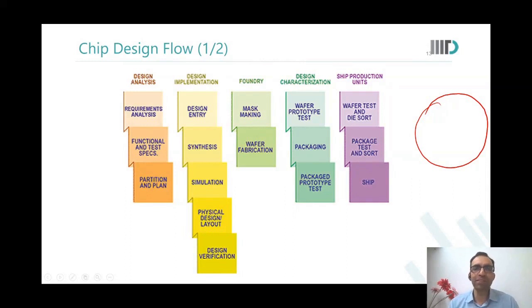But due to some reasons, it could work only at 1.1 gigahertz on silicon. Can it happen? So I need to know at what speed it is working. That is why it is called characterization. It is the characteristic of that die that this die is working at 1.1 gigahertz and not 1.2 gigahertz.